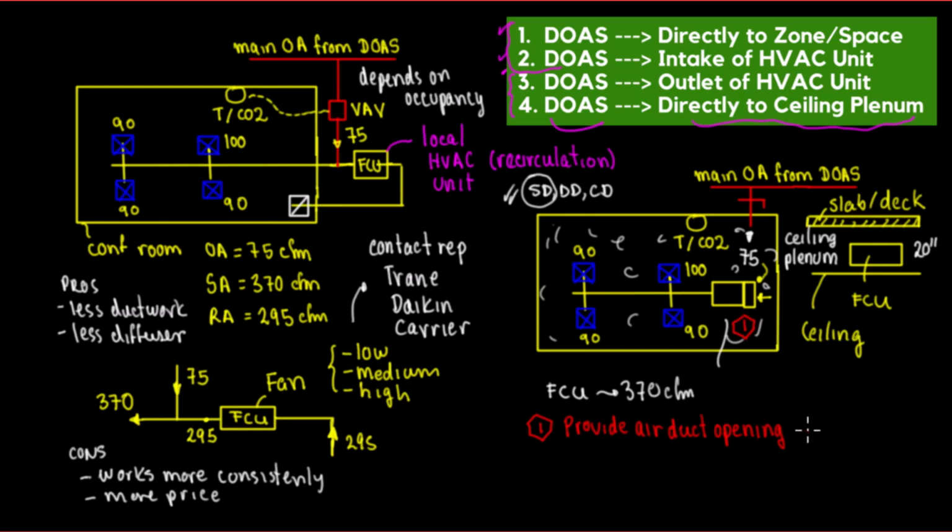And then you could include 1/4 inch wire mesh. Wire mesh, right? And of course, in a project, there's so many keynotes. This is part of our sheets. And also for this, you're going to provide a volume damper right here, so they can adjust everything.